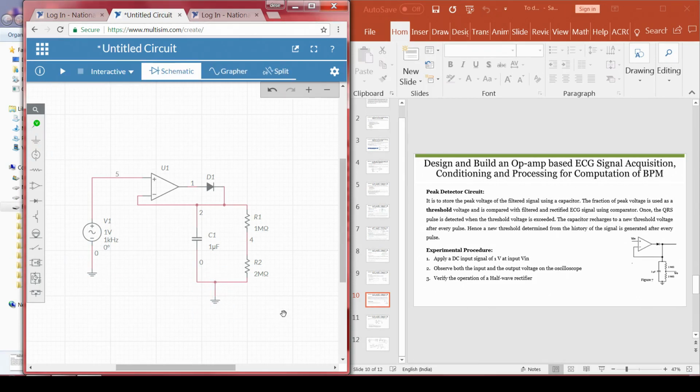What we have to measure is the output voltage at this point, and whether the capacitor output follows the input when I change the input voltage. In order to understand, let me remove this particular terminal so that there is no connection here. So, we can easily see whether it is following the peak or not. Then we will make this connection, and at this particular node, we connect another voltage probe, and we will see how the output signal looks, right.